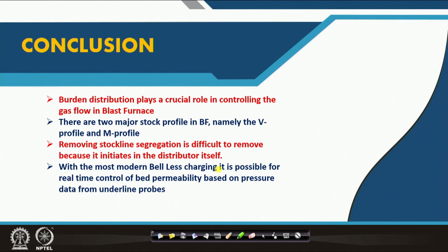And with the most modern bell-less charging, real-time control of the bed permeability is possible. Based on pressure drop data from underburden probes, you can control the burden distribution. Okay. So, as we have just discussed, this is the major conclusion, and thank you very much.